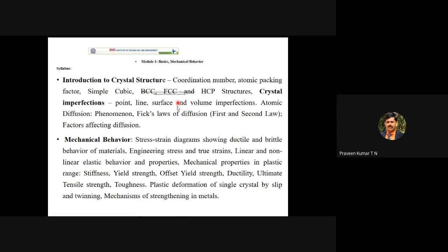in the metal. Those defects are referred to as point defect, line defect, surface defect, and volume defect. I think volume defect you can understand, especially if it happens in casting. Some space has no molten metal. Because of contraction, there may be small voids or holes inside the solid metal. Then it is referred to as volume imperfection. A huge number of atoms are missing in some region.